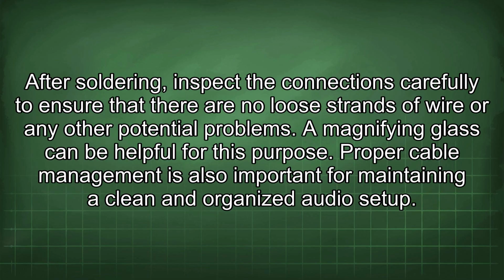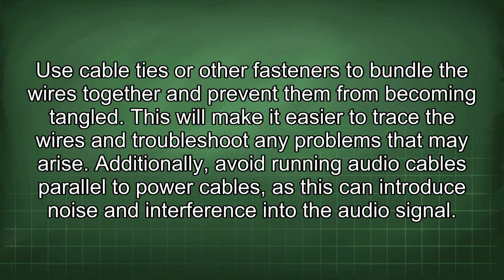After soldering, inspect the connections carefully to ensure that there are no loose strands of wire or any other potential problems. A magnifying glass can be helpful for this purpose. Proper cable management is also important for maintaining a clean and organized audio setup. Use cable ties or other fasteners to bundle the wires together and prevent them from becoming tangled. This will make it easier to trace the wires and troubleshoot any problems that may arise.